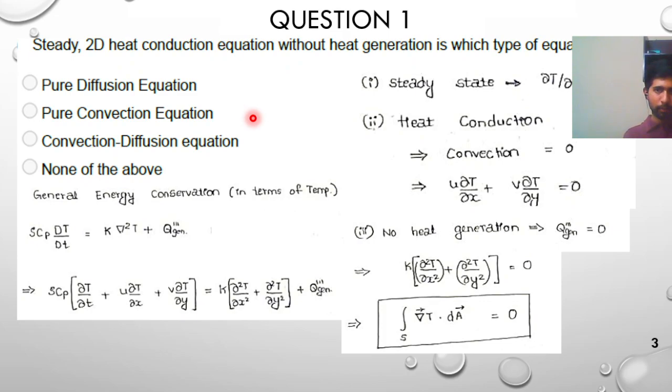In reality, pure convection is not possible, because there will be some amount of diffusion. But when we do maths and governing equations and try to solve them, we try to see which things we can ignore. It saves a lot of time without changing the results. In cases where Peclet number is greater than 10, if you ignore the diffusion term, you will get only 0.1% or less error.